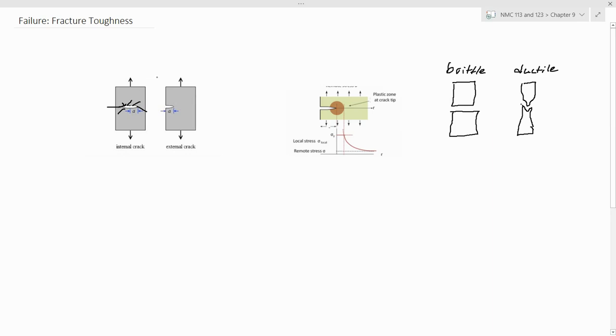But the cracks can either be a surface crack or an internal crack, depending on the specific forming of the material. If you look at the subsequent drawing on the left, this is a representation of a crack, but this is an external crack, a surface crack, and then you have a specific force being applied to the specimen, right? Say the working stress that you're applying on both sides.